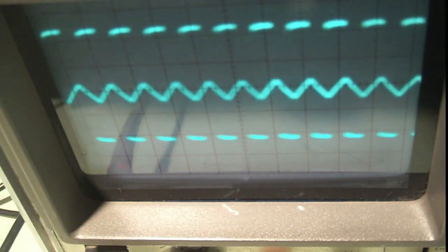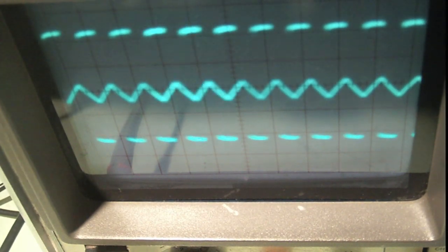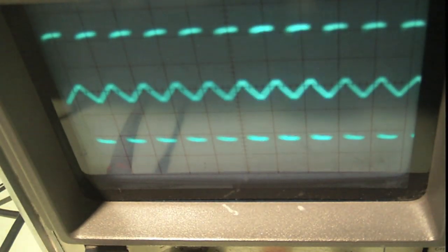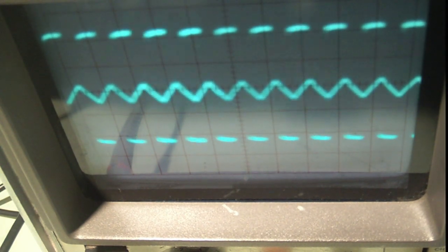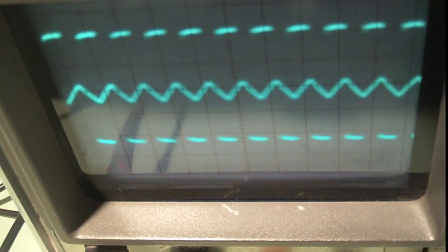But in this current design, you could get roughly a 10 hertz signal, just like I described earlier, through, one sec, let me flip to the page, through a method like this, okay? If you remember that, the sort of AM modulation type thing and this are the same thing. So not your PWM frequency, but you could actually make a sine wave out on this thing that was about 10 hertz. After that, it would start to attenuate down that signal as well as the PWM frequency. Okay, and using this method, you could create an analog value that's anywhere you like.